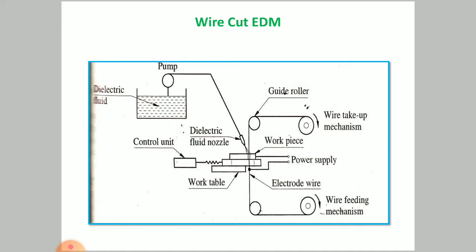You can observe here the workpiece is not immersed into the dielectric fluid, but rather it is supplied externally through the dielectric fluid pump over the workpiece, and that will carry forward and eliminate the dissociated molecules, right?